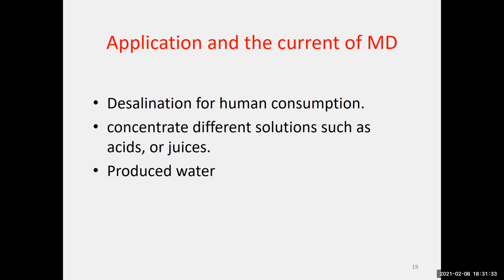We're looking at applications of MD, desalination for human consumption. There's a breakthrough that has been done by a group from Spain last year, where they came up with a membrane distillation system of much higher performance than the values that we could produce. They were saying the key for this is to have a very effective energy recovery system. But we've seen that it can deal with different qualities of water. So dealing with water of high salinity is another benefit.